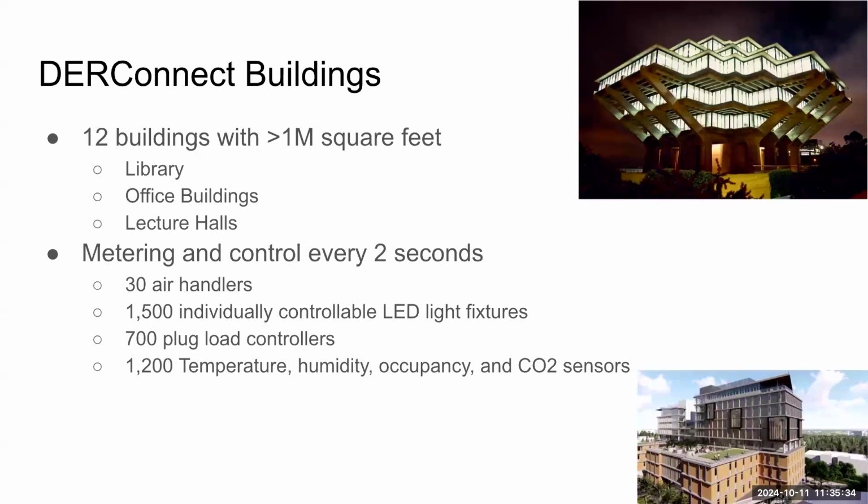Is your question more about the communication architecture, or is it more about the people using it? Okay, communications. Yeah, you're right. It has to be custom built, like our plug-load controllers. They have a BACnet server, so we have to use BACnet to communicate with them. But with lighting, they have a proprietary API that we have to communicate with. So all of it had to be manually programmed.